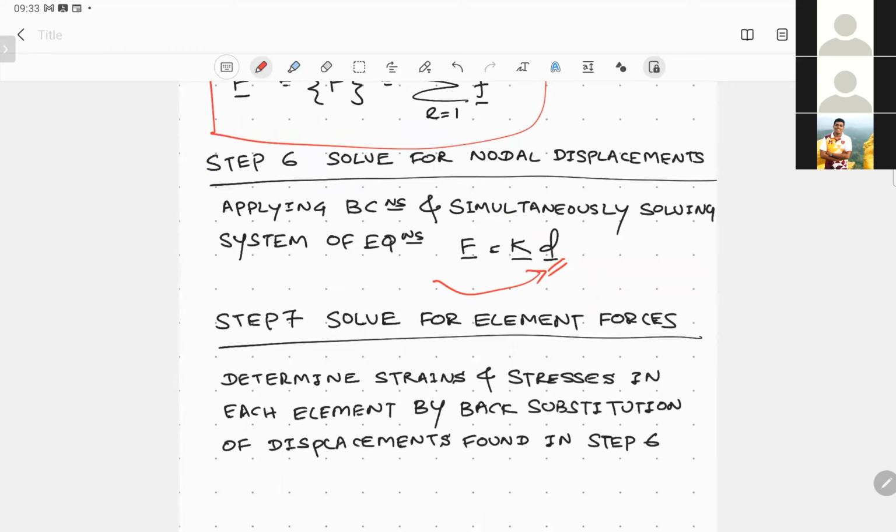When you have the nodal unknown displacements, then you can further zoom into the assembly and consider the stresses and strains to which the elements are subjected. So you can do your analysis at an element level once you find the nodal forces. So it's all about back substituting your unknowns into the element equations which you derived, and you can find the forces acting on each element and the stresses, and so on and so forth.